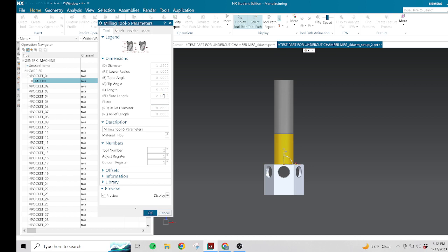All right. Parameters. Caution: do not set the tool number. It is inherited from the packet ID. All right. It's practically saying that we don't have to set the tool number here, because it's inherited from the packet, which is this one here. However, you must be careful, because depending on which machine you're using, you have to change this, obviously, right?